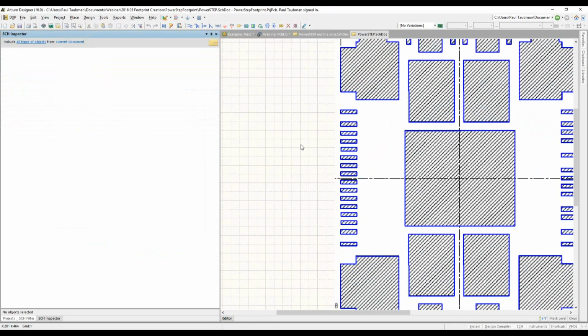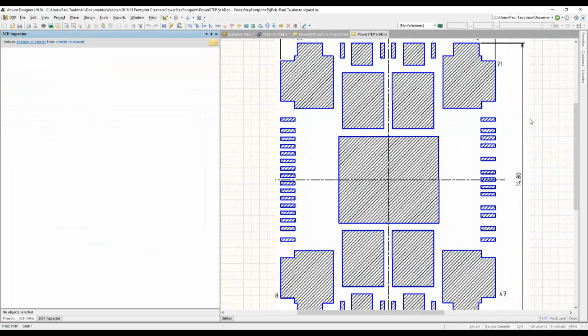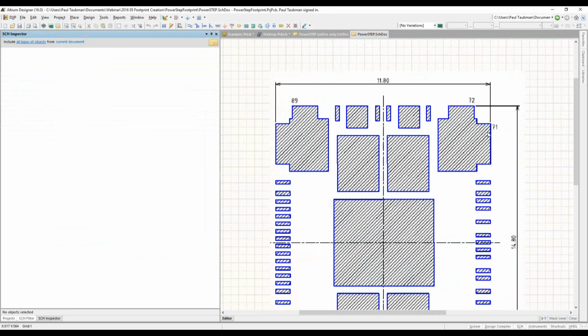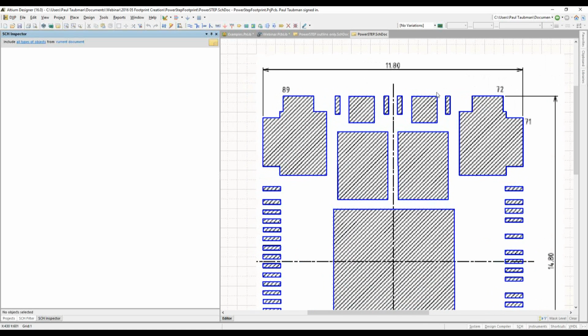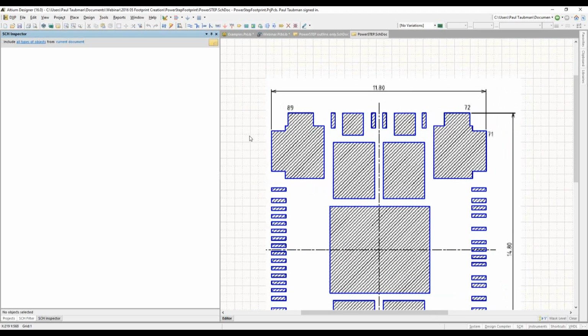Are they accurate? No. And by the way, be very careful about PDFs in general, because if they're doing any type of vectors in there, they can be off a little bit. I had experienced that when I did support with Altium many years ago. It was actually an MIT student who was trying to print these things off in a PDF and then do some type of PCB process in the lab that he had access to, and we were having problems with it because the PDFs didn't have the accuracy that he was looking for down to the 10 mil level. So just be aware that these things could be off a little bit. But wanted to give you at least one idea about how to go about doing this.